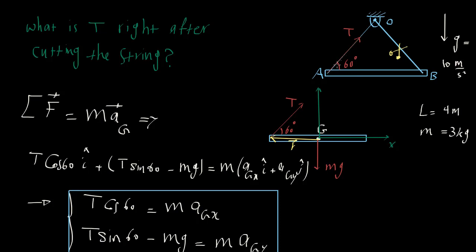So I would use the unit vector along this line to represent this line and say that the acceleration of point A should be normal to this line, and the unit vector along this line would be just cosine 60 in the I direction, sine 60 in the J direction. That represents this line.